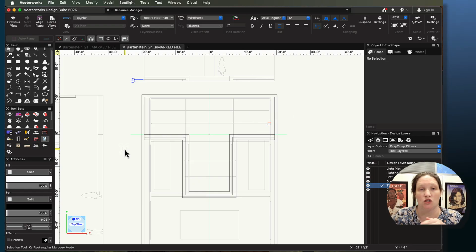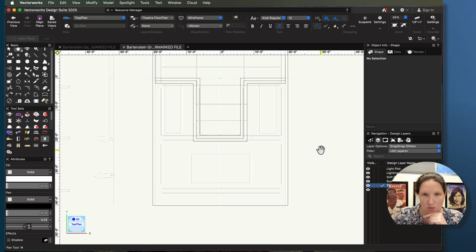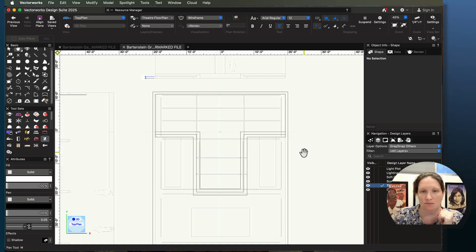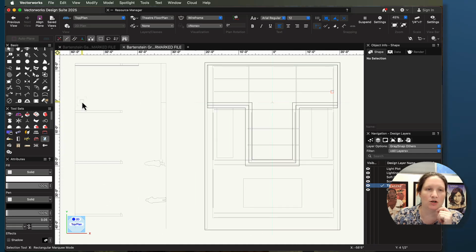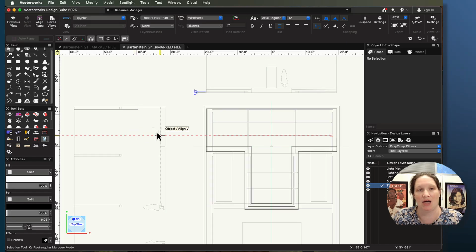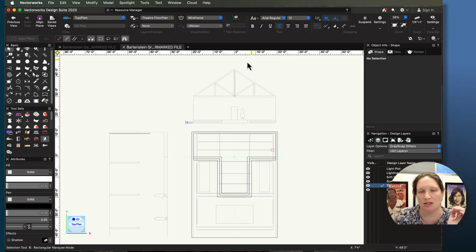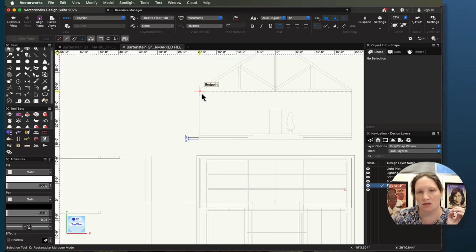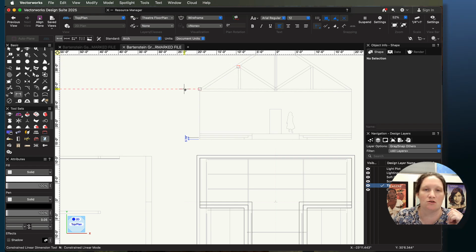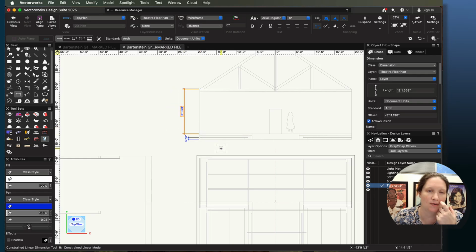We're going to use our wall tool to add walls going around the space. So in order to add these walls, the first thing I'm going to do is give myself an estimate of the height of them. This venue is an interesting shape, right? You can see it has a vaulted ceiling. So the walls, it looks like, are actually kind of ending at this point because there will be a roof here. So we will just create walls that are as tall as that, okay?